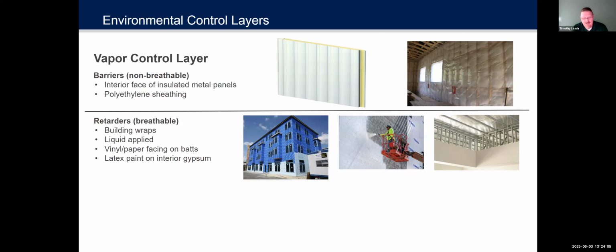But that really highlights a point for some of this other material that I want to contrast with an insulated panel. And that is, because the foam is non-hygroscopic, the metal surface doesn't absorb moisture. It is not as weather dependent in installation as some of this other material. An insulated panel, a few hours after a rain, you can continue installing because the panel is not going to be affected by the rain.